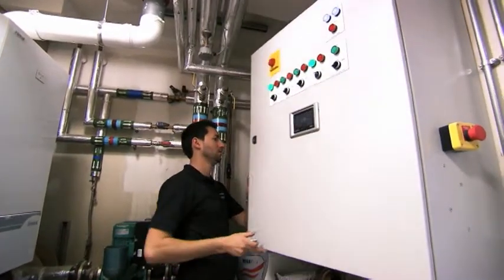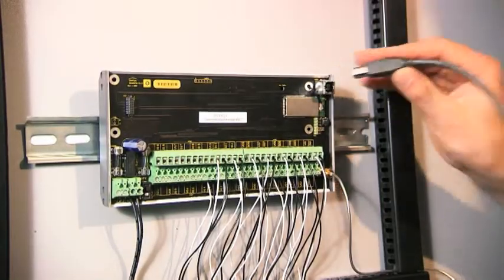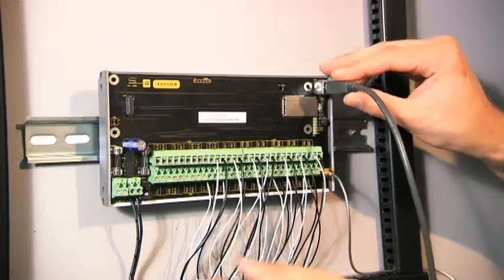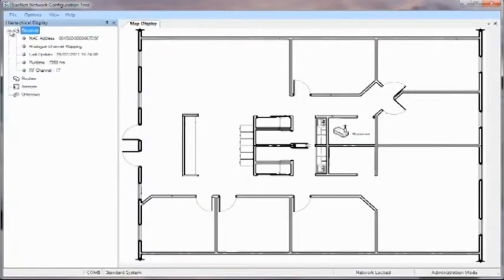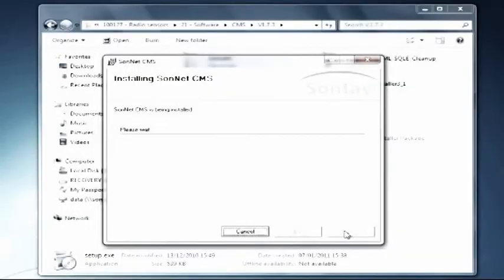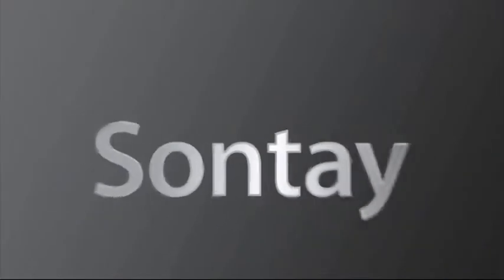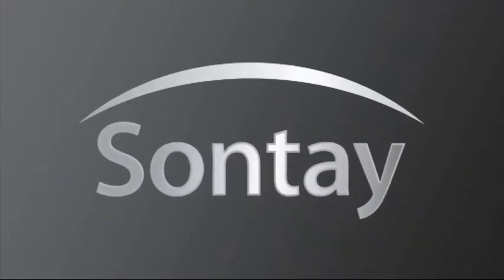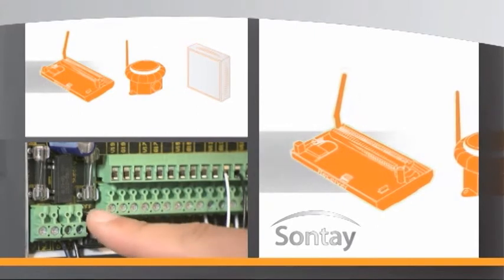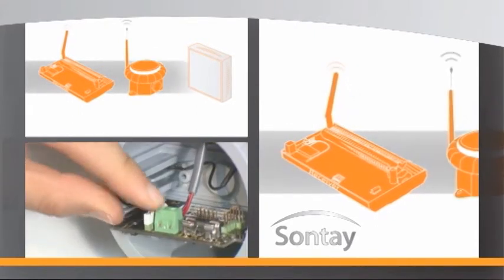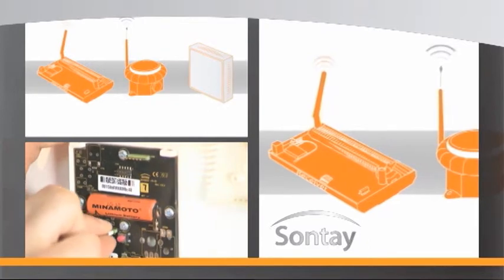First of all, with your receiver in place, connect it to the laptop using the USB cable provided and switch it on. When connecting the receiver for the first time, it will show as a new device. The process from here may differ depending on your operating system. For more information, refer to the software installation section of the video. The devices must be powered up in order of receiver, routers, and finally sensors.